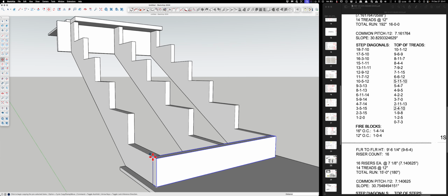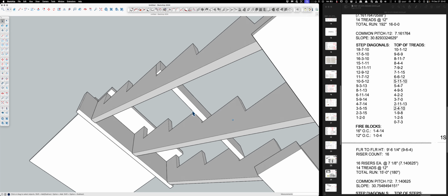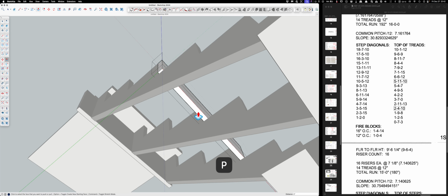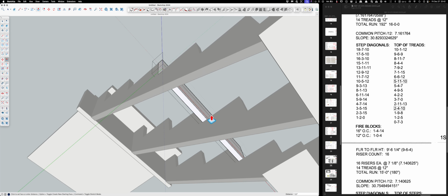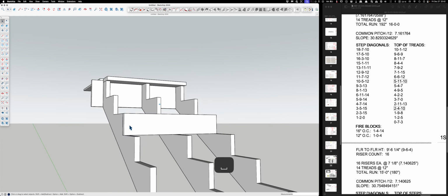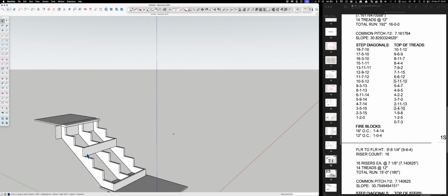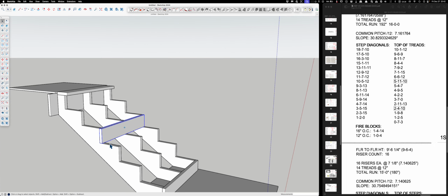But then once you have your stringers in place, you can start in the middle somewhere. Like I'll start right there. And without standing on anything, because you don't want to put any weight on anything until you get all your kickers in. So you glue the face of these, you put your kickers in, you get them flush and square, shoot 1 2 1 2 1 2, and through the magic of automation,